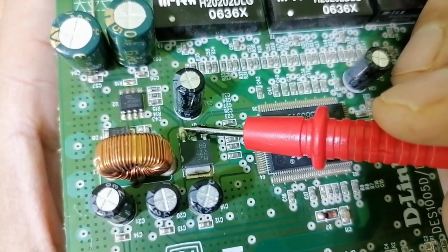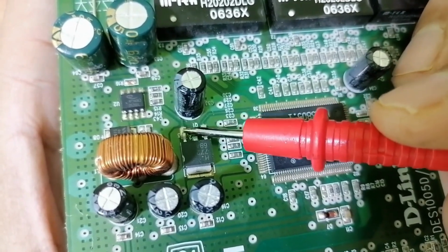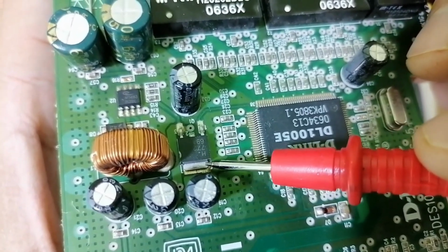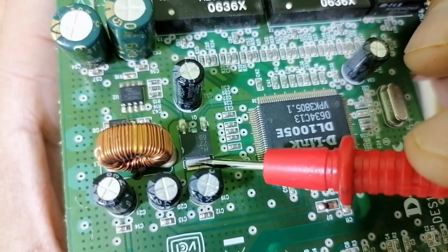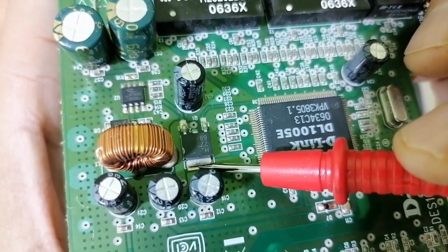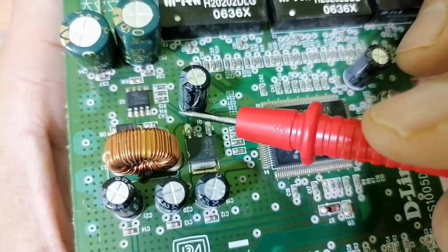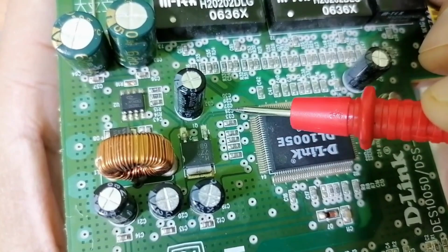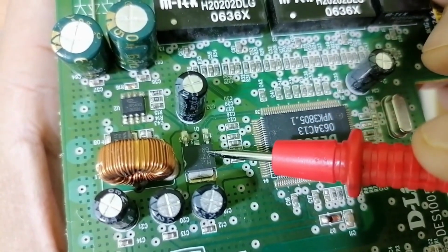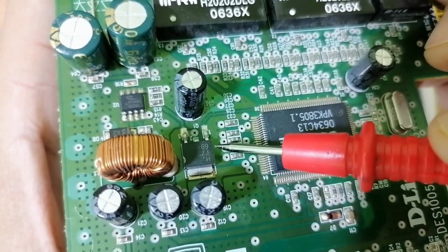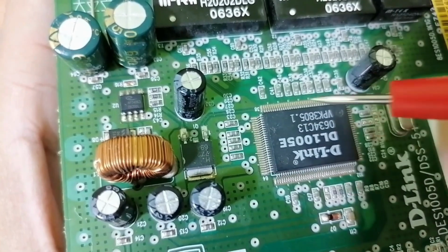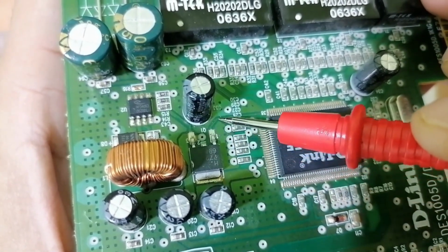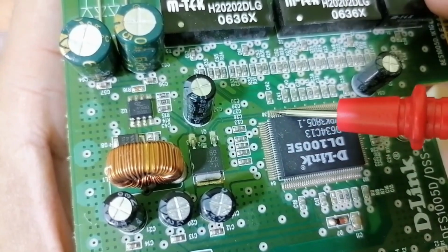And this one is basically the source. Do you see the bolded line? And here we have the drain. So the power is passed from this terminal to drain to source, as you can see. And here we have the gate. Do you see the gate? With this MOSFET, I can even know the control IC. This IC controls this MOSFET, because we have this line coming from here.